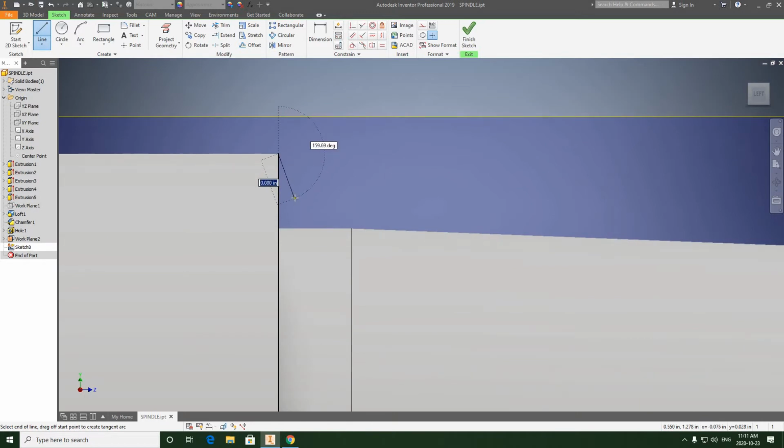And we're going to sketch a basic trapezoid shape. It has to be drawn like this, the same way a high-speed steel tool bit or carbide insert would be plunged into the workpiece to do the cutting on the lathe. Right? You're going to be starting with the smaller cutting surface first and working your way up to a larger one, like this. This is a trapezoid.